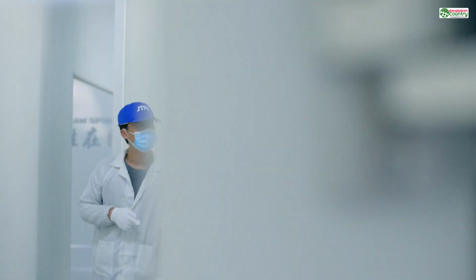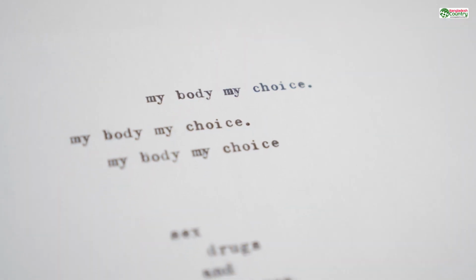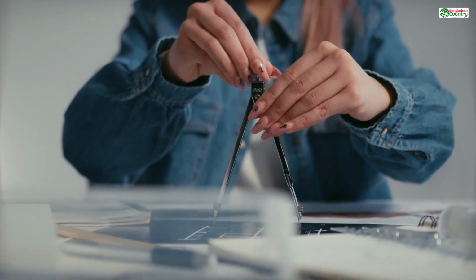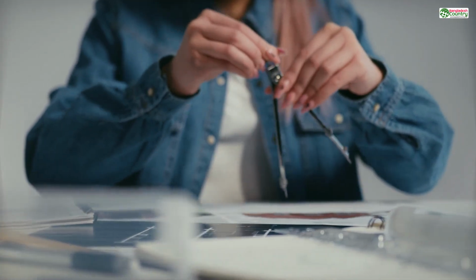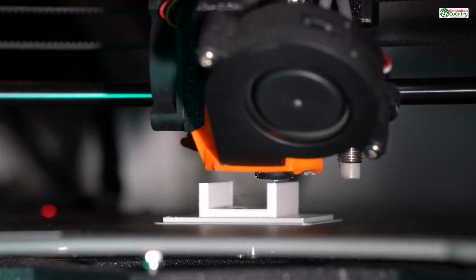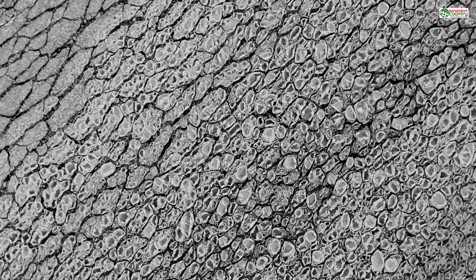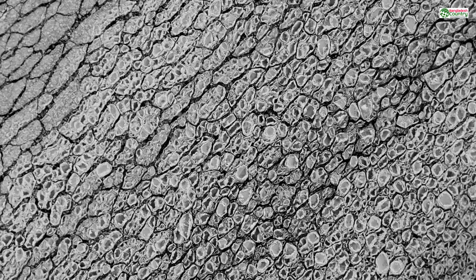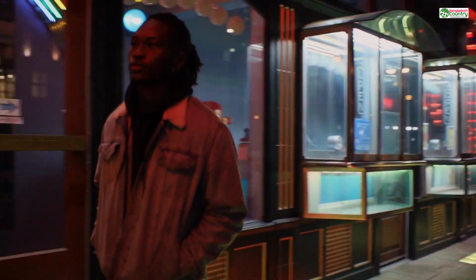Draft quality is just code for a high layer height. They're telling you this will be fast, cheap, and the layers will be visible. Perfect for prototypes. Standard quality is your Goldilocks zone, your 0.2mm setting. It's the default, the best all-around choice for most common prints. And high detail is your low layer height option. This is for when you need that museum quality finish, and you're willing to pay a bit more and wait a bit longer to get it. Your choice here directly impacts the final bill and the quality of the object you hold in your hand.